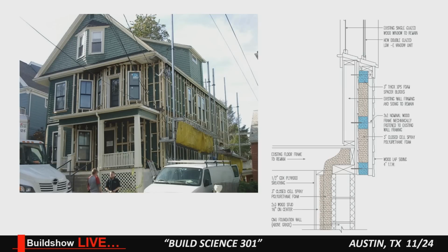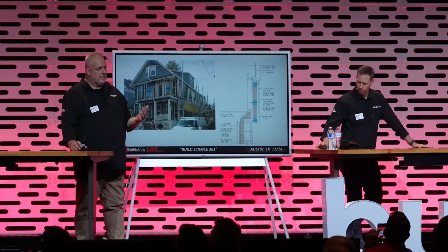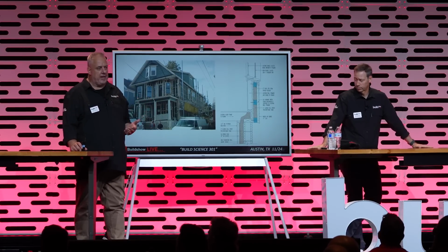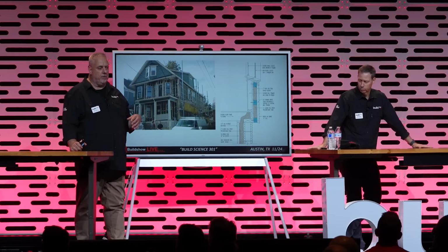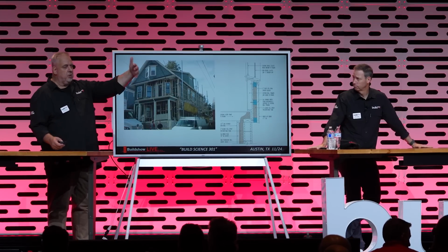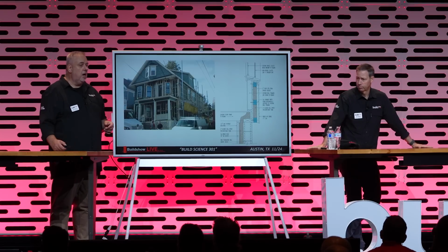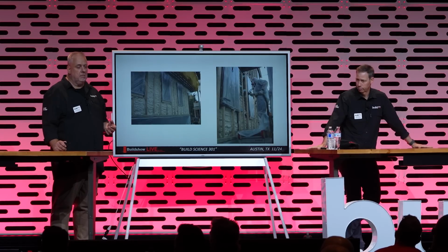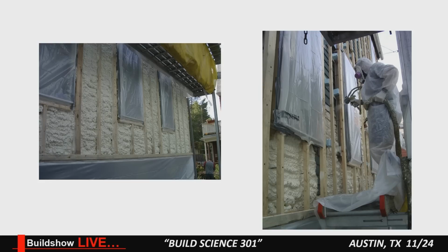And this is where it stemmed from. This is actually a remodeling project that I did with another builder in the Boston area where he had really nice details, nice rosettes, window trim, wood windows. And he said, I want to do a zero energy house, but I don't want to take any of that stuff off. Is there a way we can do it from the outside? I said, sure, we'll just pad out a wall, we'll fur it out, we'll turn it into a Yeti cooler, and we'll get some double glazed windows and we'll put those on the outside of your single glazed windows and call it a double glazed storm window assembly. And that's exactly what we did, right? Notice that all of the blocks there, they're all thermally broken. The wall is plumbed off the XPS blocks, and then we foam everything in place.